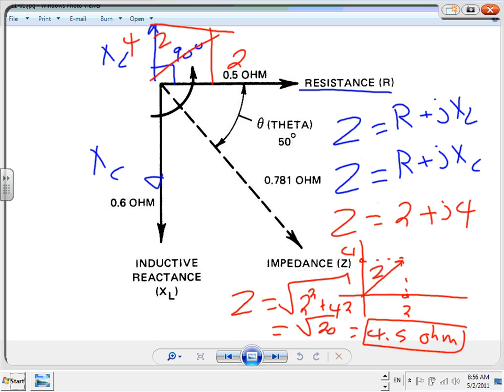Resistive, capacitive, inductive. 90% of the time, guys, you have resistive and inductive loads. Capacitive load, you add it. There's no value for the capacitive load except correcting the inductive load.